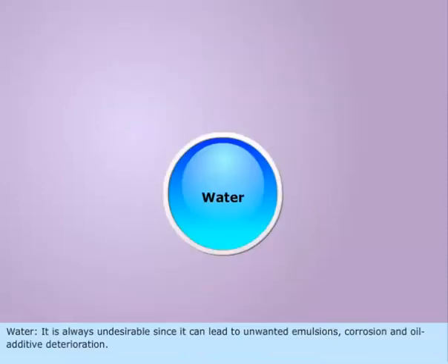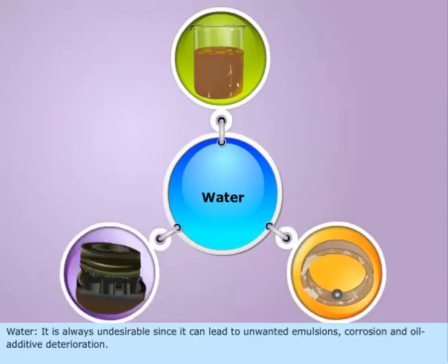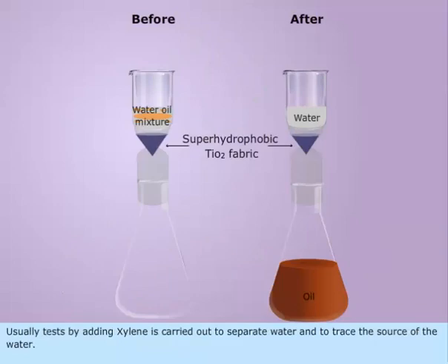Water. It is always undesirable since it can lead to unwanted emulsions, corrosion, and oil additive deterioration. Usually, a test by adding xylene is carried out to separate water and to trace the source of the water.